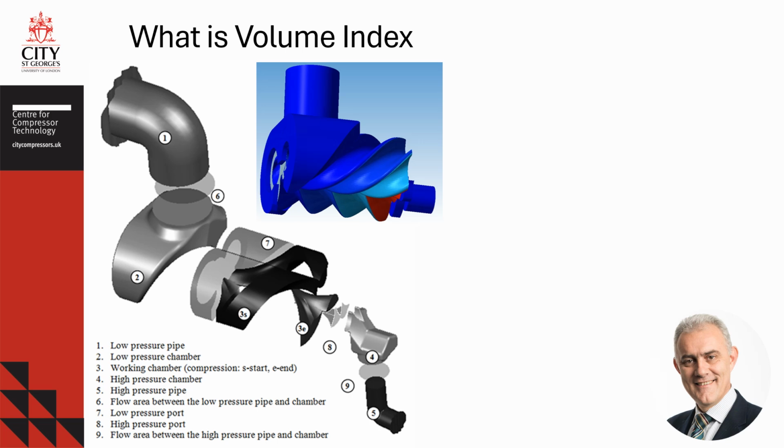The compressor domain and flow areas in a screw compressor are shown in this image. The dark shaded domains 3S and 3E represent trapped volumes between rotors and the casing, at the start and at the end of the compression process, respectively. Surface area 7 represents the axial and radial suction ports through which the fluid enters the rotors, while the gray shaded areas 8 show the discharge port through which the compressed fluid leaves the compressor rotors through the discharge plenum 4 and discharge pipe 5.